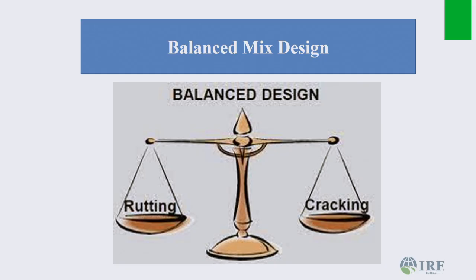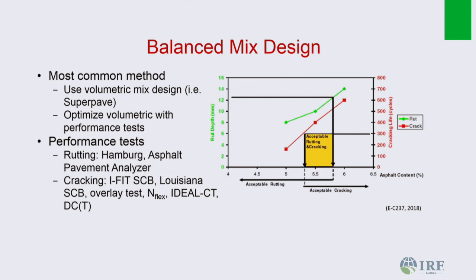You should be able to know, like she rightly said, if there is an alligator crack, you should be able to identify that this is an alligator crack, and these are the possible causes. Okay. Now, in balanced mix design, what they seek to do is basically optimizing the mix such that you are able to, and maybe you talked about it yesterday, balance both rutting and cracking.